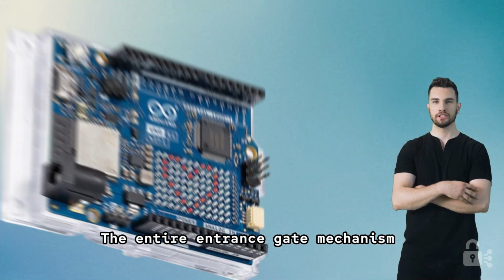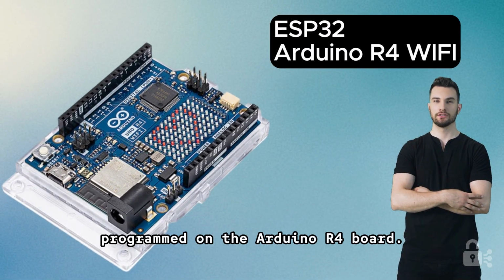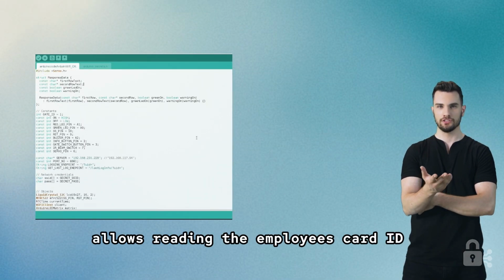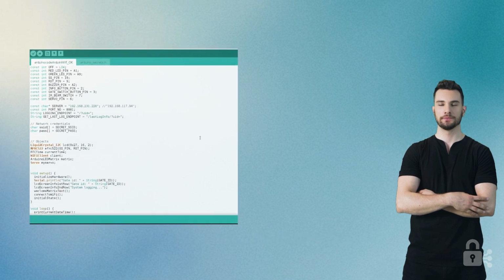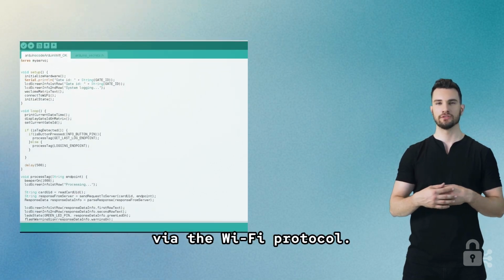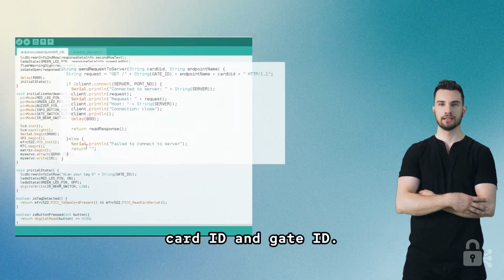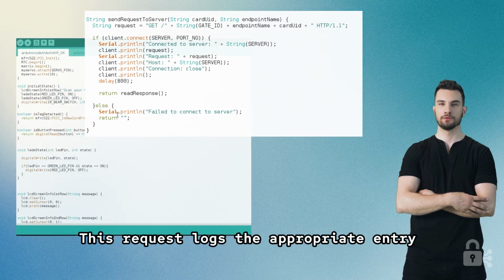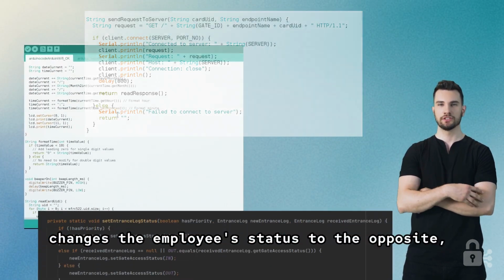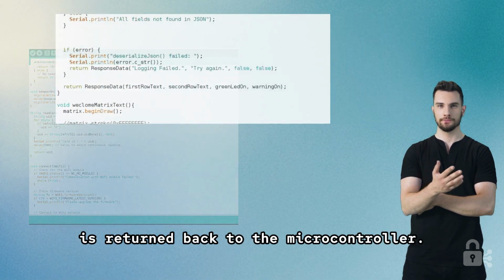The entire entrance gate mechanism is controlled by an ESP32 microcontroller, programmed on the Arduino R4 board. The microcontroller's source code allows reading the employee's card ID through the RFID reader, then sends an HTTP request to the appropriate endpoint of the application via the Wi-Fi protocol. The request is sent with 2 parameters, card ID and gate ID. This request logs the appropriate entry in the application's database, changes the employee's status to the opposite, and the response information is returned back to the microcontroller.